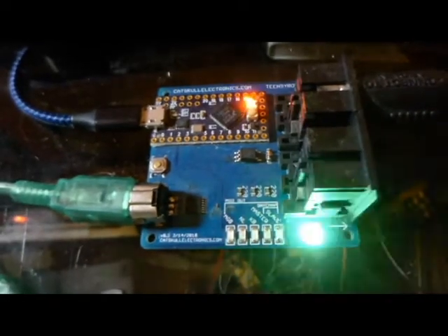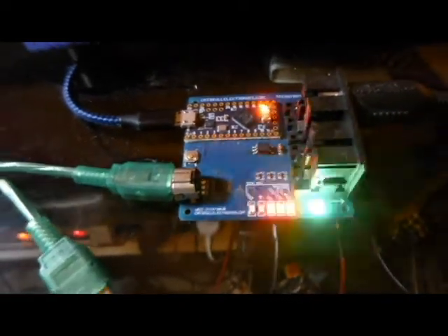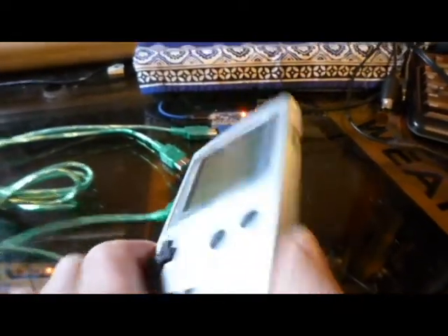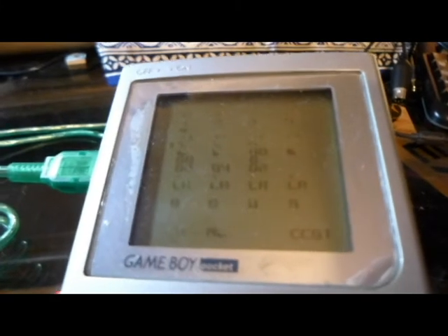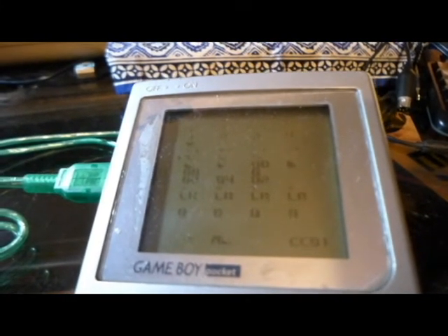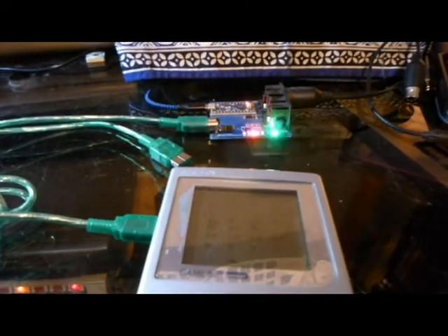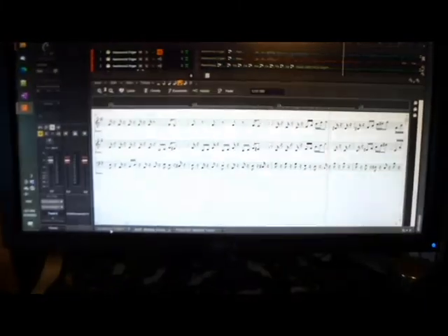The TeensyBoy lets you send MIDI data into a game link cable of a Game Boy. A cartridge called MGB, which is sold with the TeensyBoy, gives you front panel controls over things like which waveform to use on which channel, the envelopes, etc. But again, you don't have to control all that using the Game Boy. You can actually modify any of it by sending the right MIDI commands. For example, MGB maps controller 1 data to the pulse width of the square wave for that channel.